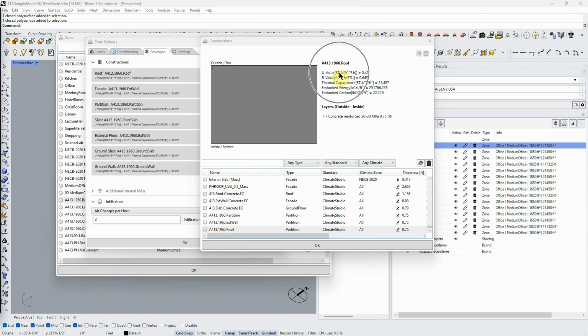This would be kWh, kilowatt hours, if it was in a much more sensible metric system. A BTU is how much energy it takes to raise the temperature of a pound of water 1 degree Fahrenheit. Why the hell that has anything to do with what we're talking about, I don't know, but it's how somebody experimenting in some lab came up with something that then became the standard. That's the problem with the IP system. It's very arbitrary. Anywho, R value is the reciprocal of U value.